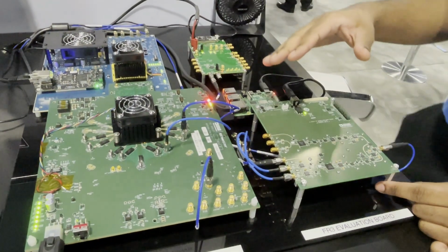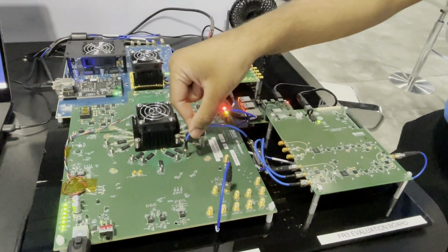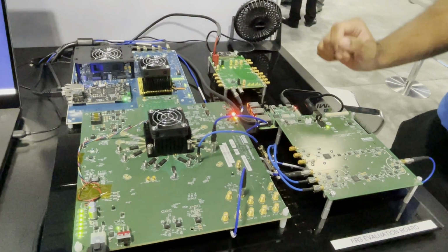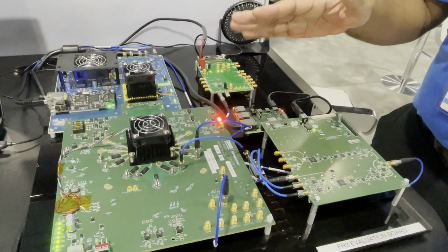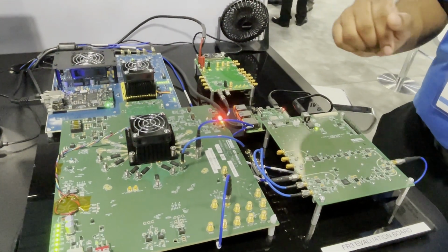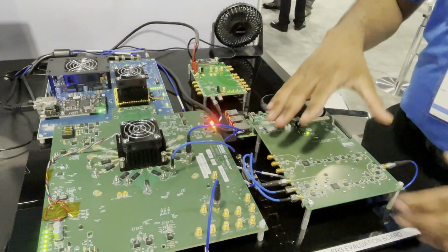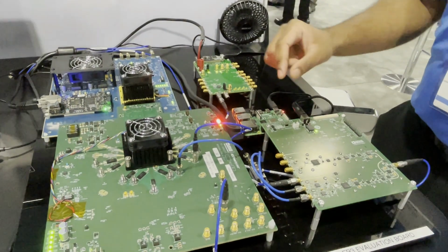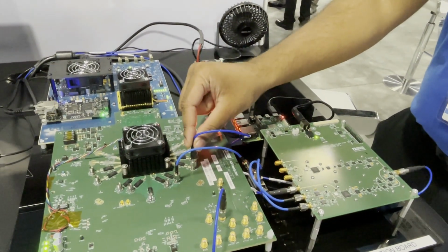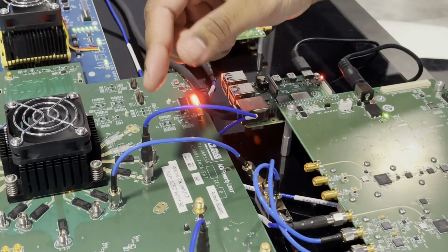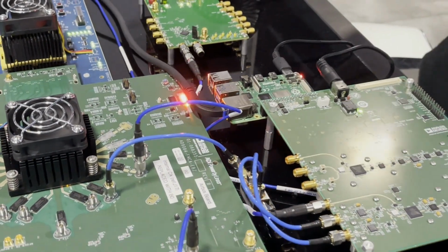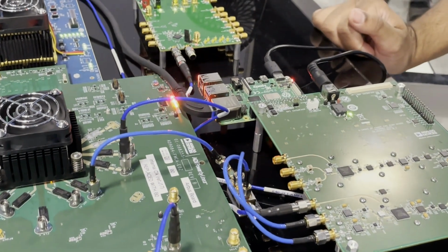And what's happening is basically we're utilizing the DAC and ADC of the Apollo MXFE. The DAC can go all the way up to 20 gigahertz. We're sweeping the NCO frequency on the DAC from 7 to 16 just to show the capabilities of the FR3 board. And we're also using the ADC. The ADC has instantaneous bandwidth up to 10 gigahertz, but we're only utilizing it at a fixed IF, so we don't need that kind of bandwidth for this application.